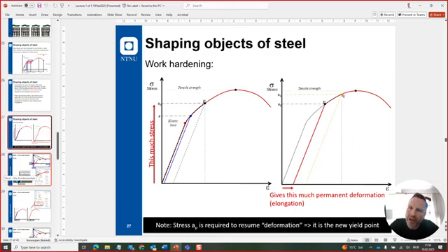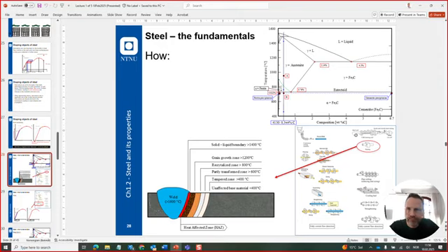The other manufacturing process is welding. Very often when you have seen a steel item that has been welded and has failed, you will see that it is typically taking place next to the weld. When you are welding, that takes place around 1600 degrees or more. It's a completely melted part. This is the weld in blue. What takes place in the ground material that you're welding together is that there is like a heat affected zone.